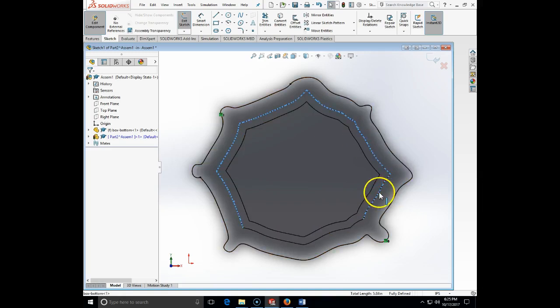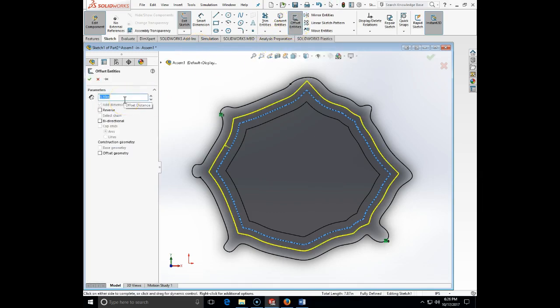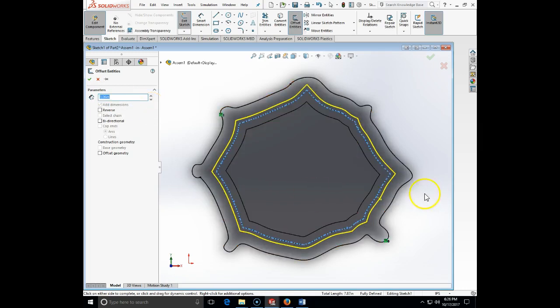The inner contour, I'm going to offset outside by 0.1 inch, because that will be my spacing for a tolerance. So that will be my slight fit. Actually, I will put 0.06 inch outside so that it is a total of 0.1.